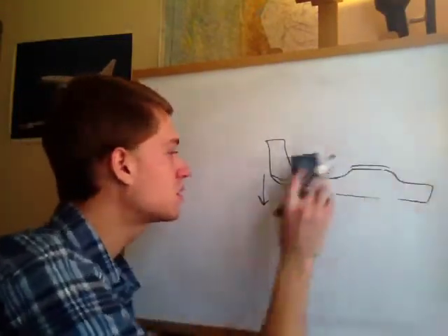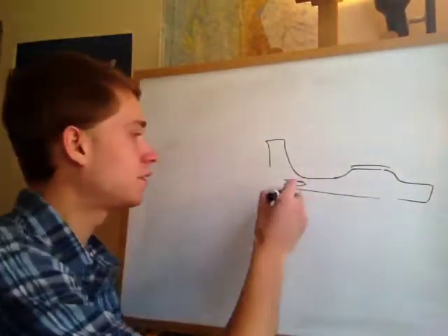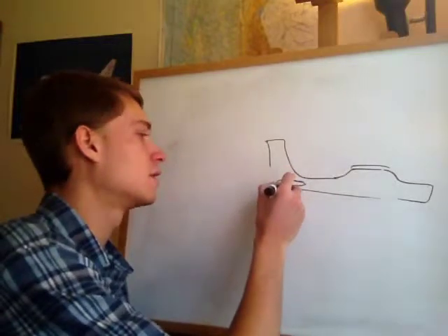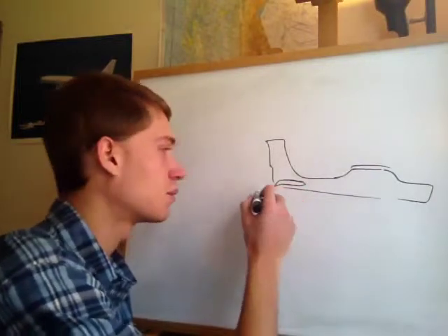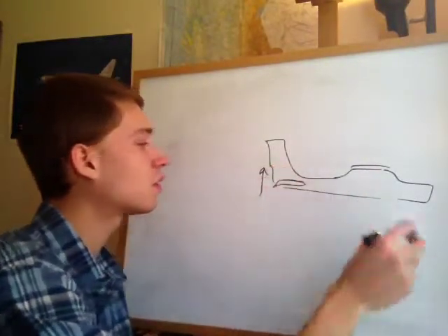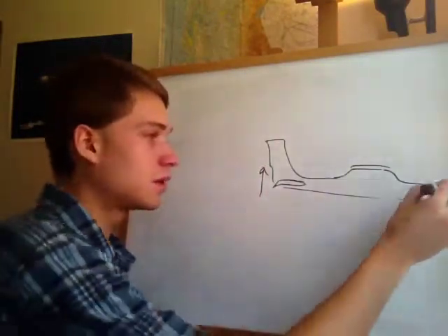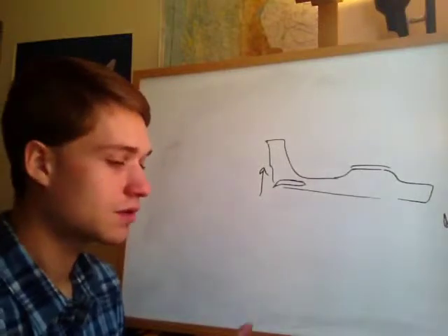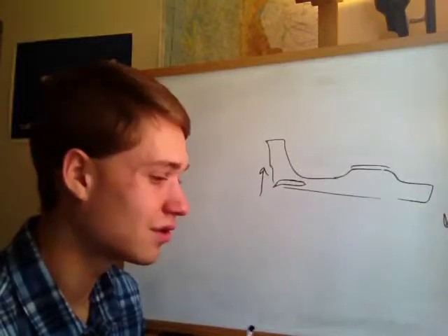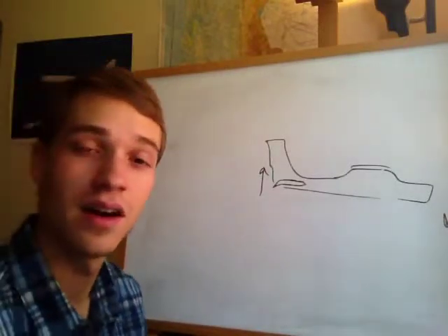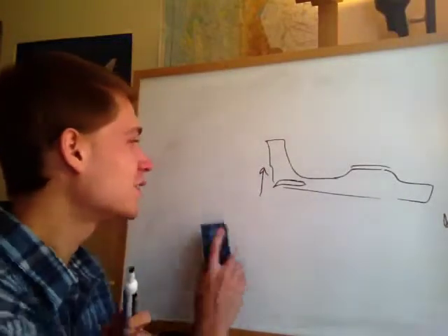Opposite is true if you want to bring the nose down. So you push forward on your yoke control, that will deflect the elevator downwards, and so now this back wing over here is going to be producing more lift than it was before, and so it'll have an upward force on the tail. If you bring the tail up, you're going to bring the nose down. Okay, so that is how we can control the airplane with our elevator controls. And so we have just talked about all three primary controls. Now we're going to go into the secondary controls.